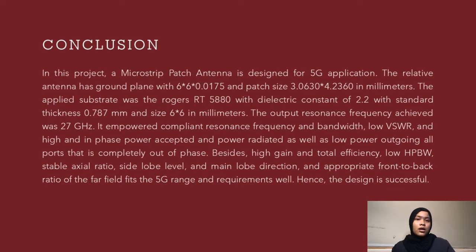So it has compliant resonant frequency and bandwidth, low VSWR, and high, in-phase power accepted and power radiated, as well as lower power outgoing all ports that is completely out of phase. Besides, the radiation lobe of the frequency gained in the application shows that it fits the 5G range and requirements as well. Hence, the design was quite successful.